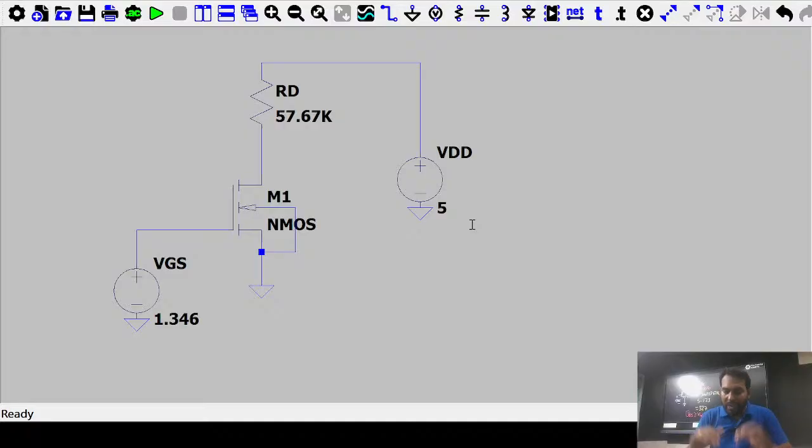So for our understanding, as circuit designers, we are not going for that much amount of verification. I am just assuming this is okay for me. Just like you have a binomial, 1 minus x to the power minus 1, this is 1 plus x plus x square upon 2 factorial plus x cube upon 3 factorial, just like this. And let x square be very small, x cube very, very small, x to the power 4 very, very, very small. So you just put 1 plus x there. Just like this, you have a lot of parameters. We can avoid them, so we are just assuming it. I am just assuming that this MOSFET is ideal. So lambda is 0, gamma is 0.